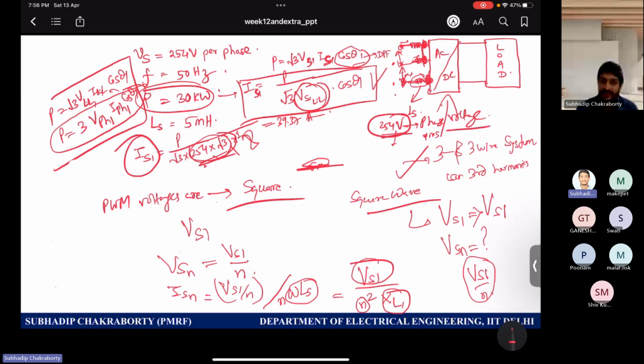By a simple phasor diagram, right? If I know that this side is purely sinusoidal Vs and Is I know to be unity power factor. So Vs minus j Is XL, okay? Because this is an inductor, right? So how will the phasor diagram look like? Multiplying by j means plus 90 degrees anti-clockwise. So j Is XL, since Is is like this, Is into j is like this, because this is the anti-clockwise direction, you take it to be positive.